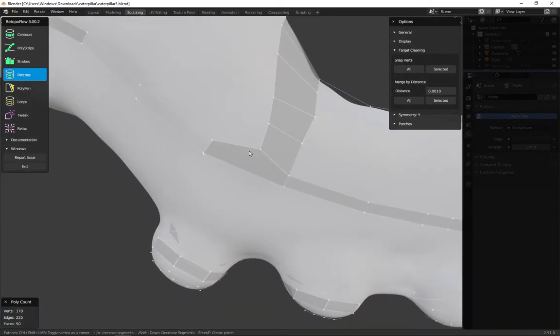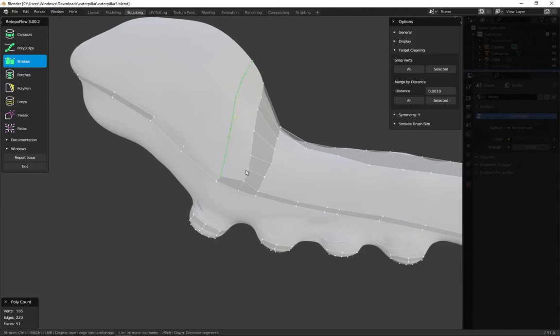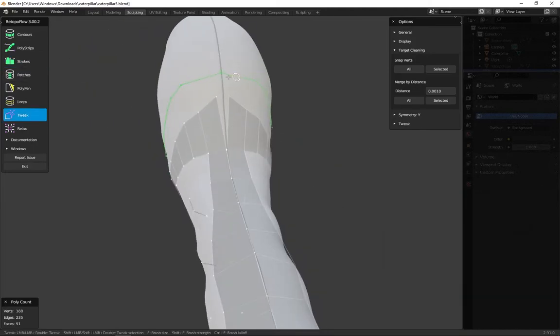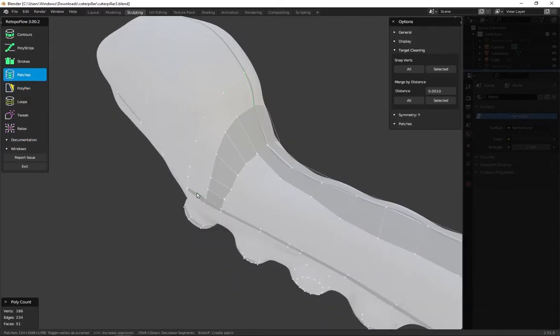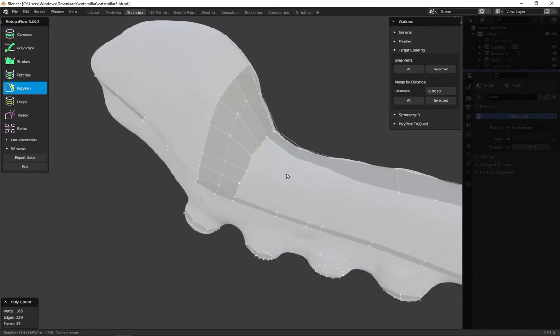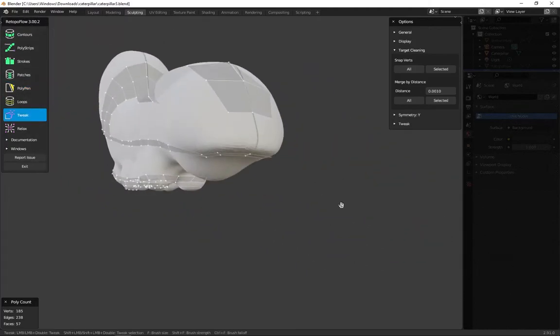When it works, this tool feels pretty powerful, but for the first couple hours, it was pretty frustrating to predict how I needed to draw these lines in order to properly have it fill in the polygons. One thing that it took me a while to master was making sure I had the same number of vertices in the two lines that I wanted to fill in.